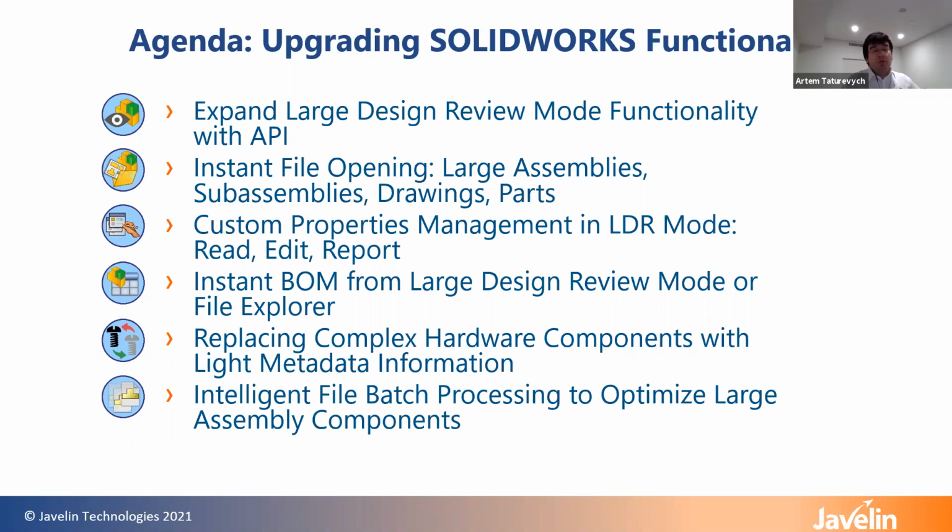Yeah. So when you process files in the batch mode, for example, when you're doing an update, quite often, especially when those files are in SOLIDWORKS PDM, you need to make sure that they are processed in the right order. And it could actually be a deal breaker for a SOLIDWORKS PDM administrator if your existing batch operation tool just processes files as they are. They should be processed from children to parents.